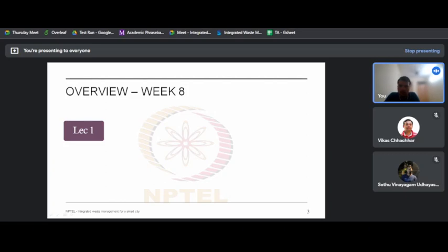Firstly, lecture 1 was about stoichiometric combustion. Using chemical balance equations and balancing the equation, we try to obtain how much oxygen is required for the combustion of the waste material. Then based on how much air or how much oxygen we need, we design the combustor.